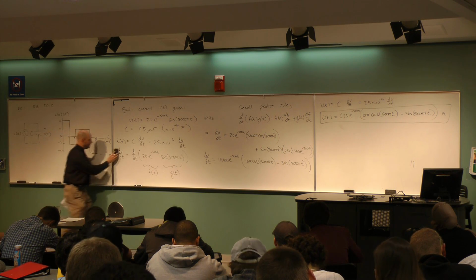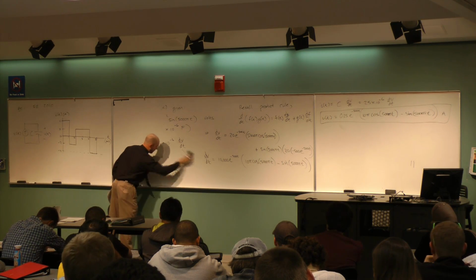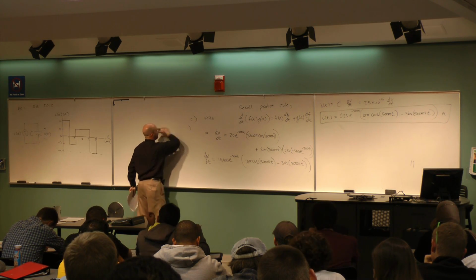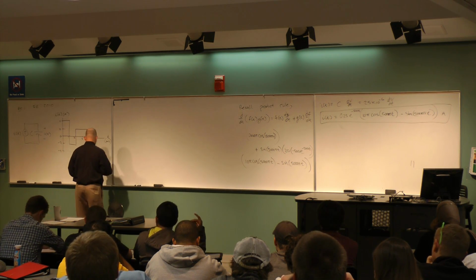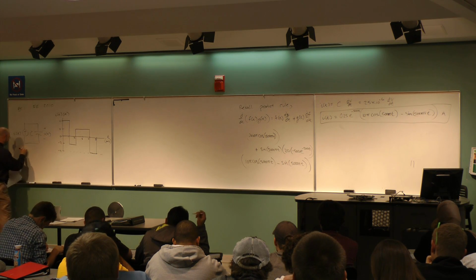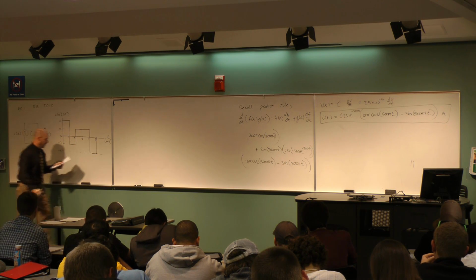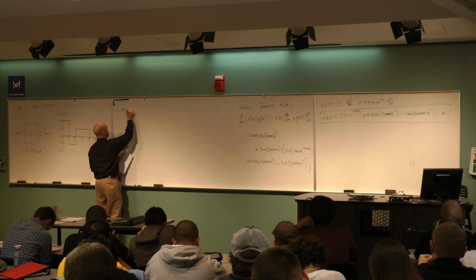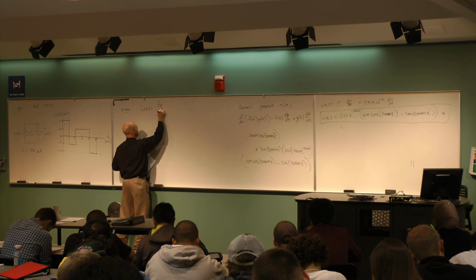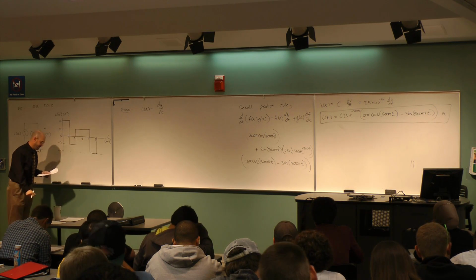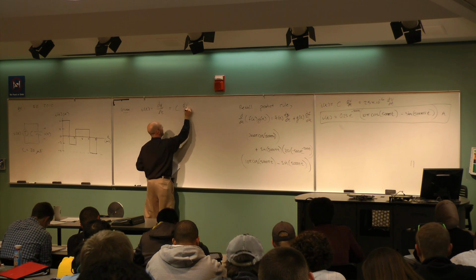All right, so here's what I would like to do. Given our basic definitions of current, voltage, charge, and a capacitor, I want to use that information to sketch some of this action. The capacitor here, we know what it is: it's 20 microfarads. By definition, i(t) is the derivative of the charge, dq/dt, which is the same across a capacitor as C dV/dt.